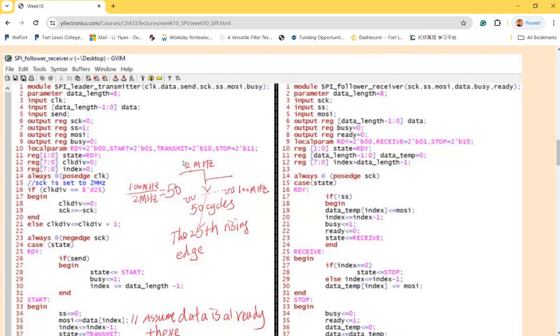No matter how fast you operate it, it's going to run following the rising edge or falling edge, no matter how you define it in the Verilog. It's the same thing as your SPI, right? If you have a clock synchronizing the operation, you can even use a switch to run the SPI communication. But now we are trying to make it faster, and you can run it at somewhere around 1 megahertz or a little bit higher than that, but usually 1 megahertz is the standard rate.